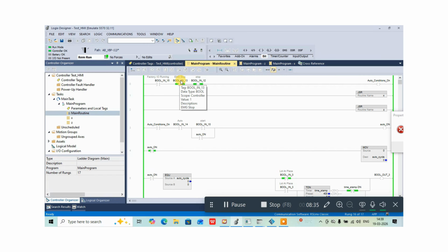Even if we press it, the input will not reach the PLC and it will not show as emergency stop or stop, so it does not give the input. If we use an NC element, if any wire is broken or anything happens, the input will directly stop going to the PLC. If it breaks, it means the emergency is activated. Safety is the most important thing during machine running time.